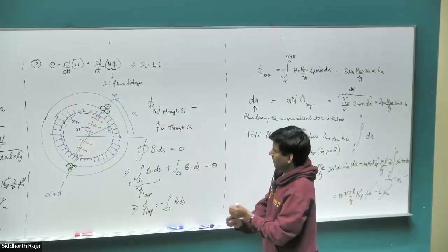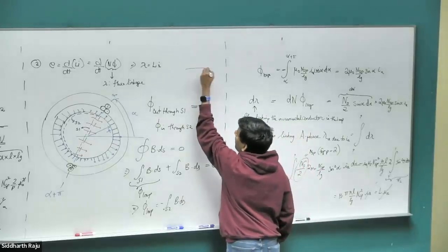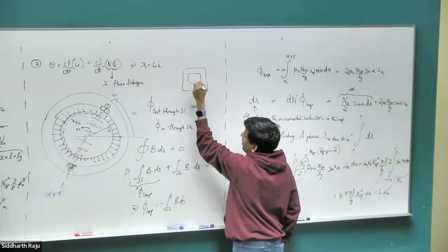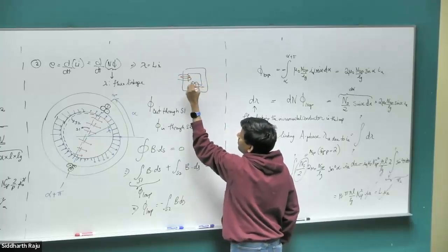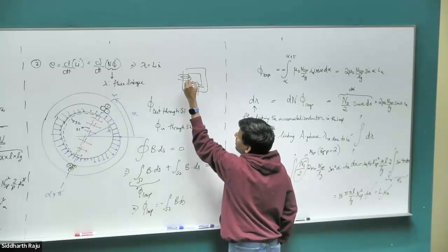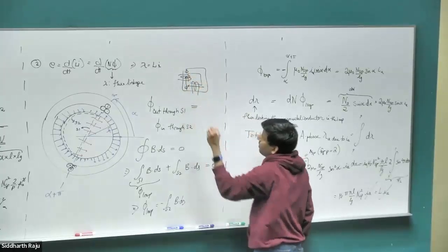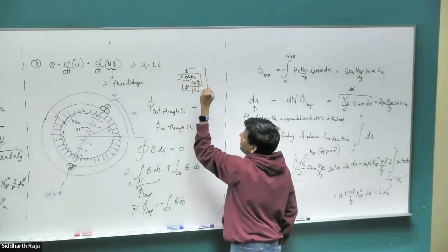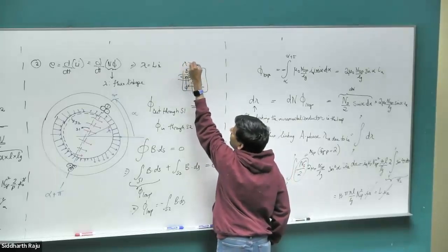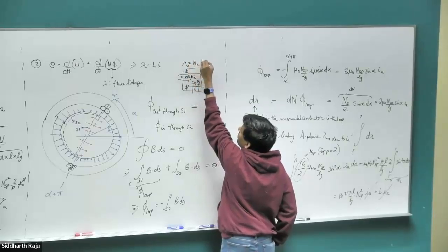At this point, I hope all of you have an intuitive feel for fluxes. Flux linkage is just, if you have some coil and it's creating some flux φ, this flux goes and links another coil. Let's say there is N2 number of turns, N1, right? The flux linkage of the second coil would be N2 times φ.